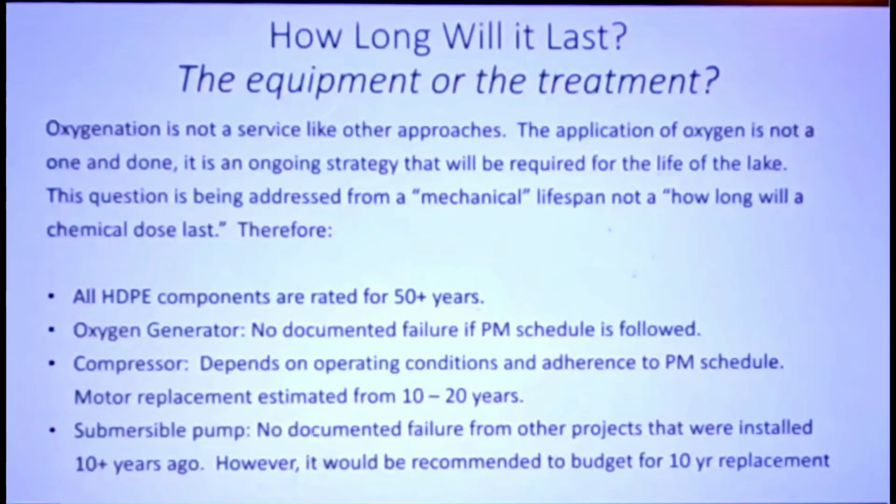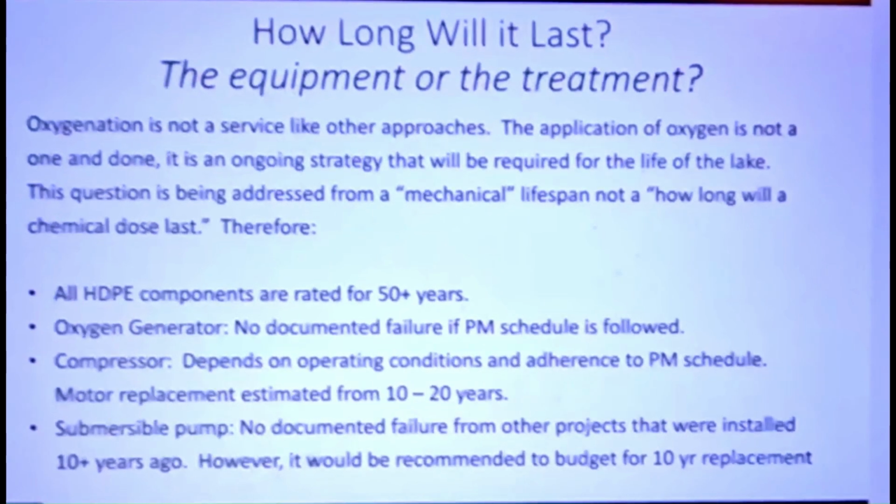If you follow the PM schedule, a rough estimate is that you replace the motor in 10 or 20 years, but you don't have to replace the entire compressor, just components. The only other mechanical equipment is the pump in the lake, and to date I know of no failures from the pumps that I've installed in 10 plus years of operation. However, I would budget for a pump once every 10 years as a ballpark factor.